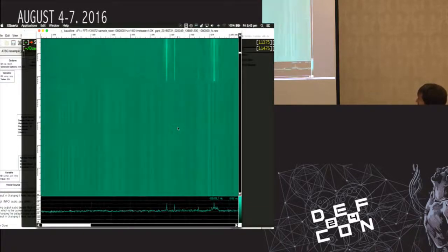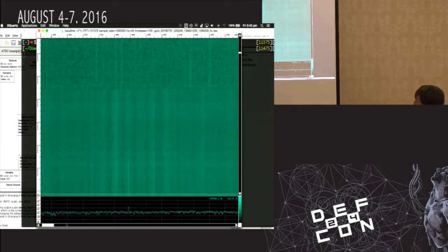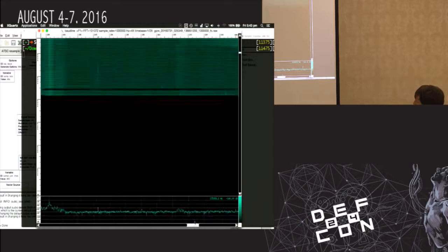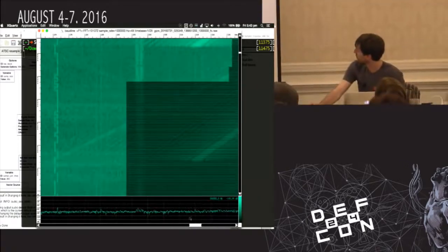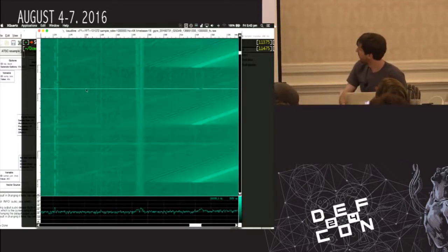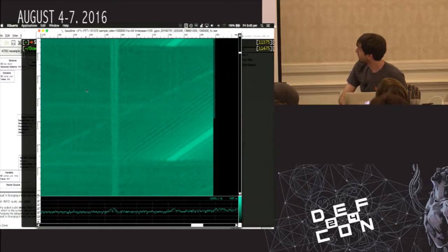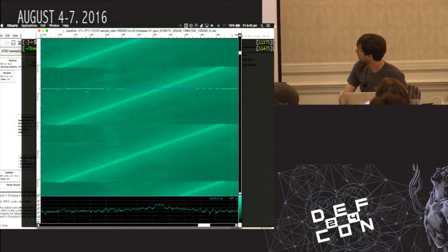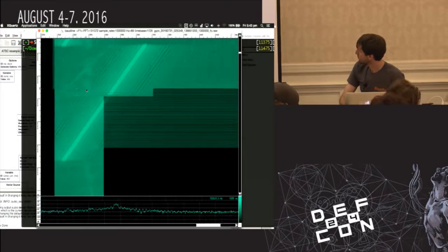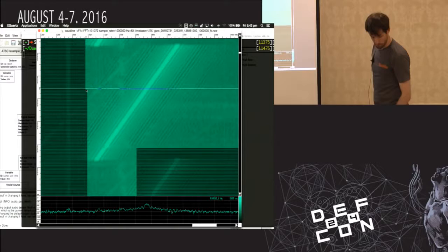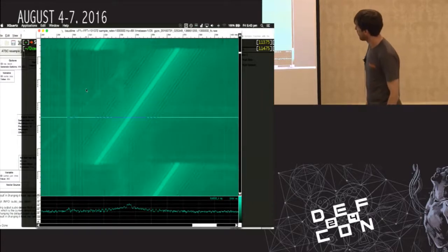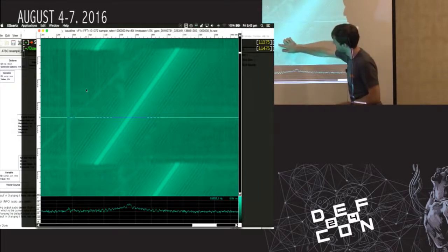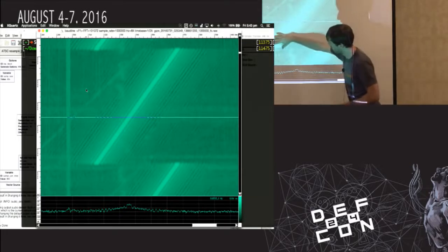and we can also zoom in terms of frequency. Where is it? Is that it? You've got all these other cool signals there. So there's our chirp, and what's interesting is that you've got what looks like this main lobe, the central signal, and then you've got all these side lobes there.